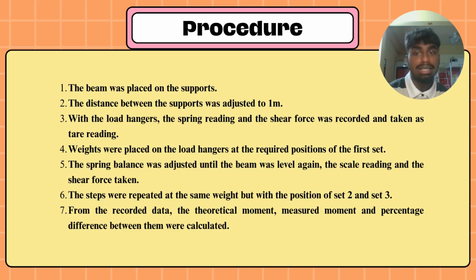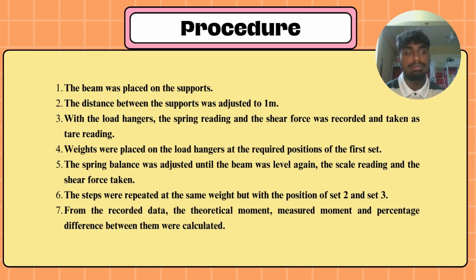The scale reading and the shear force were taken. The steps were repeated at the same weight but with the positions of set 2 and set 3. And finally, from the recorded data, the theoretical moment, measured moment and also the percentage difference between them were calculated.